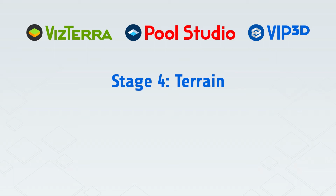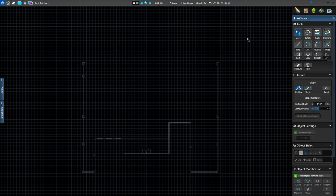This video will explain Stage 4, Terrain. The Terrain stage allows you to customize the terrain to create elevation and grades in both 2D and 3D. First, we'll work in 2D. In the panel, we have two options, multiple and single slope. We'll start by reviewing single slope.